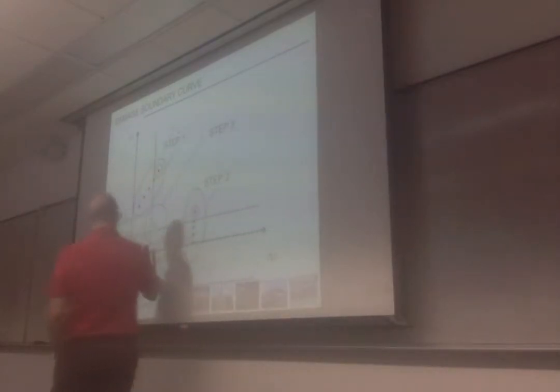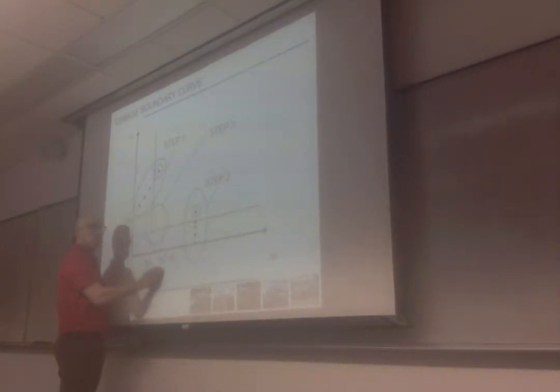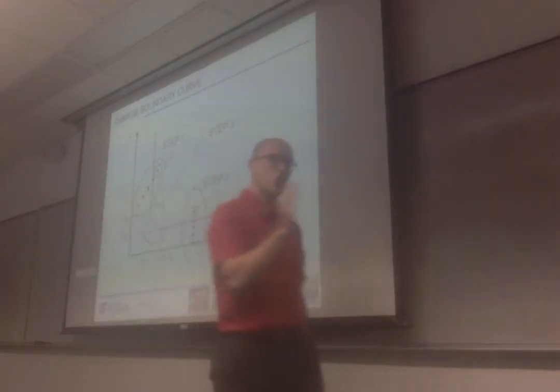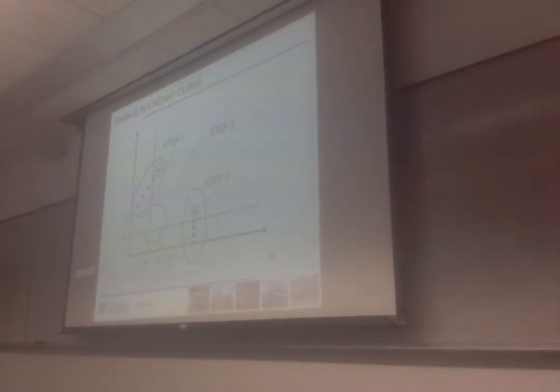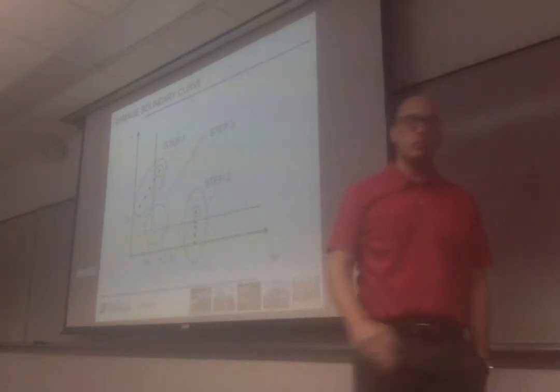To do that, we need to pick a drop height that will give us a velocity change past this point. A lot of sources, including ASTM, tell you to use a value of pi over 2 times the critical velocity change. But to make sure that you're past this, typically what you do is twice the critical velocity change. If you select a drop height that gives twice the critical velocity change, you know that you're going to be past that curve, and clearly on that flat portion of the damage boundary curve right here.